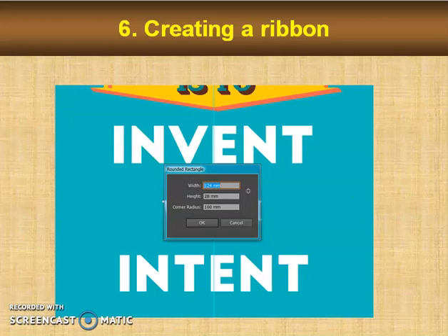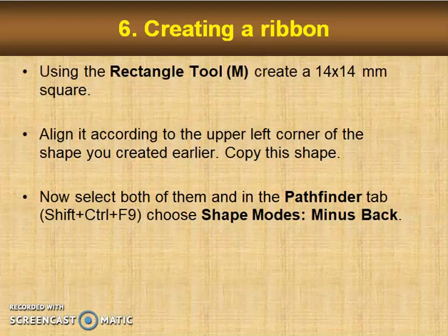Open the software and practice. Use the rectangular tool. Create a 14 by 14 mm square. Align it according to the upper left corner of the shape you created earlier. Copy this shape.